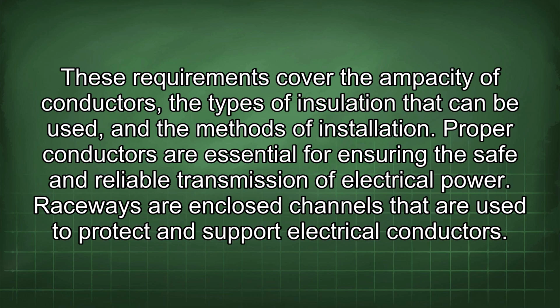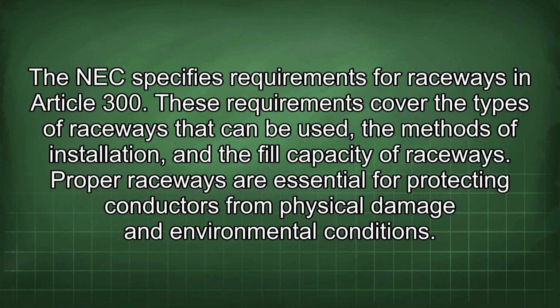Raceways are enclosed channels that are used to protect and support electrical conductors. The NEC specifies requirements for raceways in Article 300. These requirements cover the types of raceways that can be used, the methods of installation, and the fill capacity of raceways. Proper raceways are essential for protecting conductors from physical damage and environmental conditions.